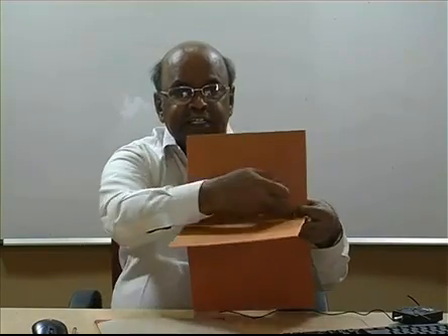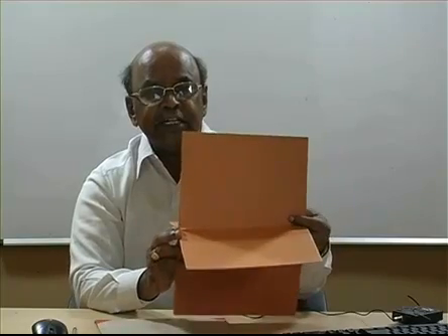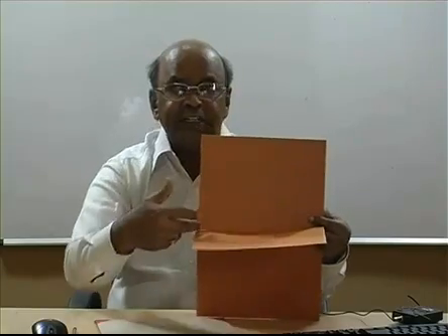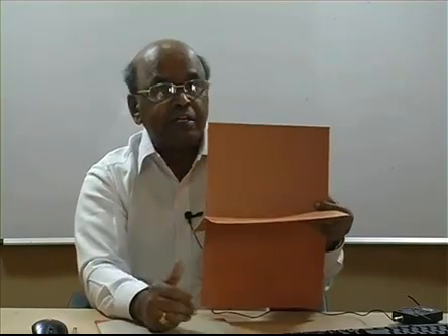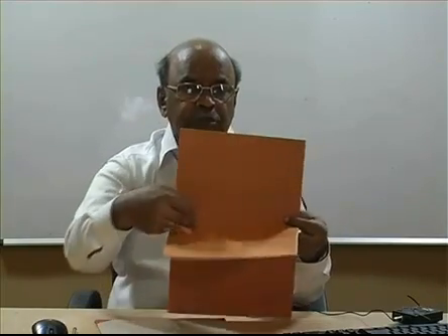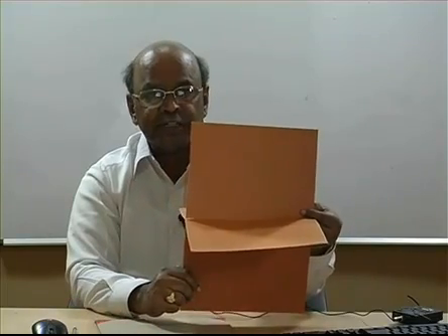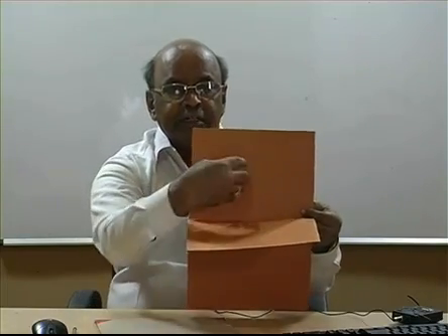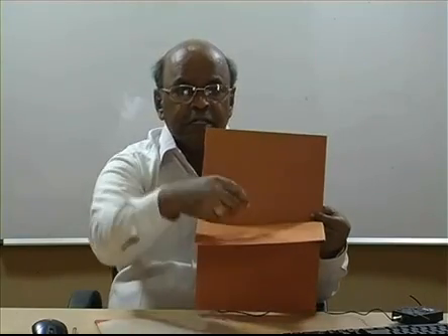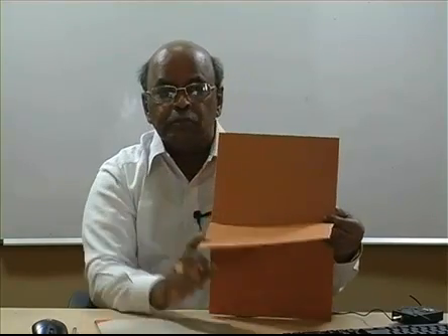the line of intersection of these two planes is called the reference line, and it is named XY. So the two planes intersect along a line just like two walls intersect along a straight line. So this is a common line. Reference line is called line of intersection, represented by XY. So you get the front view on the vertical plane by seeing from the front, and when you see from the top, you get the projection on the horizontal plane.